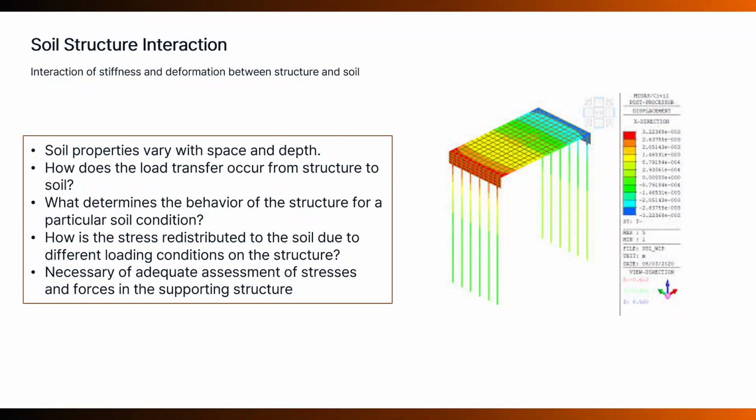And we also know that there are a lot of material models for soils that simulate the behavior of the soil under unloading and reloading conditions. So these vary with the type of soil, the loading conditions, and also the type of application, like is it an excavation process, is it a direct loading, or is it a seismic event, etc.